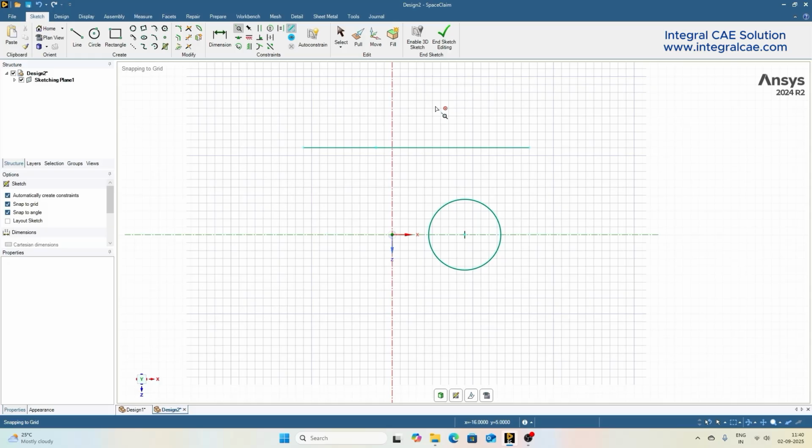You can see that the points now have become coincident and the lines have been moved accordingly, since the point belongs to that particular line. You would have noticed that the order of selection is important here. The entity which is selected next will be moved towards the first selection. So you can choose the action accordingly for selections.